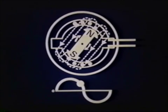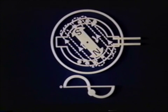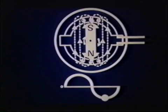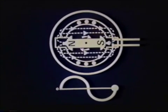As the field continues to rotate, we see less lines being cut, therefore a reduction in current flow, until again, the field has reached a point of no cutting of lines and no current flow. But now, as the field continues around, it enters the second half or negative side of the cycle and continues to build to a maximum negative current flow. Again, the field starts to move out of the coils and the current starts to decay until the field reaches the end of the cycle, where again no lines of flux are being cut.